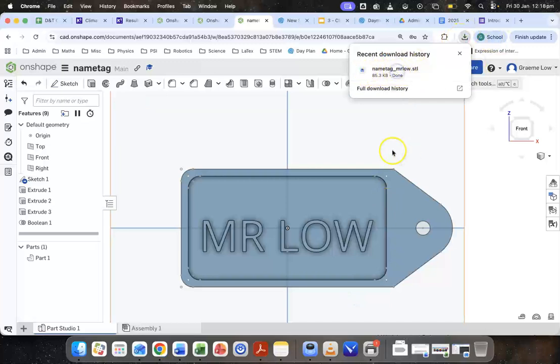So if you click on that, it opens up a 3D viewer so that you can 3D view it. But in terms of getting it 3D printed, once you've got that STL, you would send it to me, and then I would send it to the 3D printer and get it done. It's up to you how you do it. It's probably better to share the document with me, because if there's a problem with an STL, you can't really edit it beyond basic operations. If there's something seriously wrong with it, you can't really fix it, is what I'm trying to say.